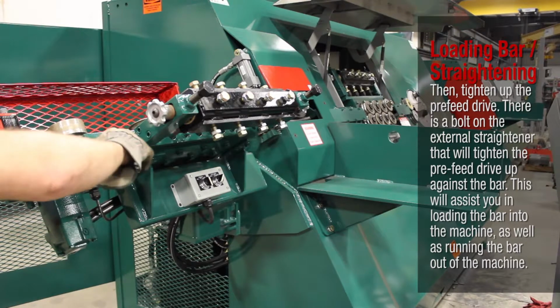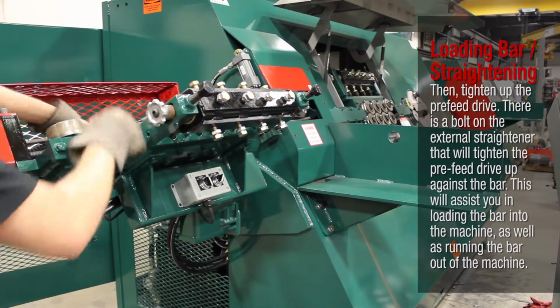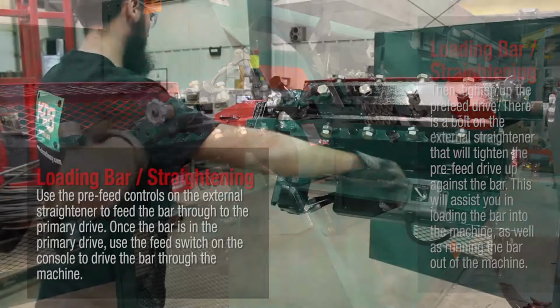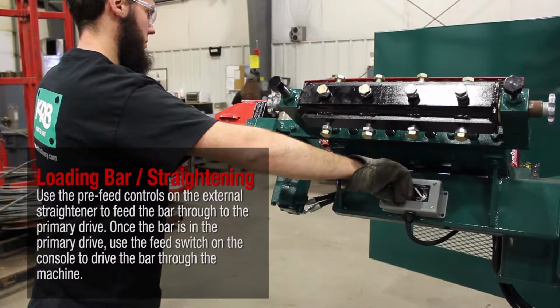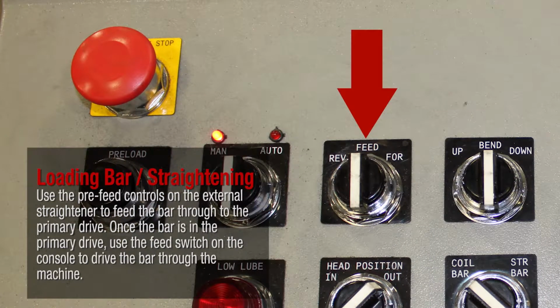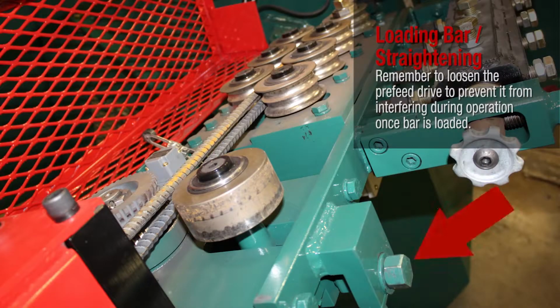There is a bolt on the external straightener that will tighten the pre-feed drive up against the bar. This will assist you in loading the bar into the machine as well as running the bar out of the machine. Use the pre-feed controls on the external straightener to feed the bar through to the primary drive. Once the bar is in the primary drive, use the feed switch on the console to drive the bar through the machine. Remember to loosen the pre-feed drive to prevent it from interfering during operation once the bar is loaded.